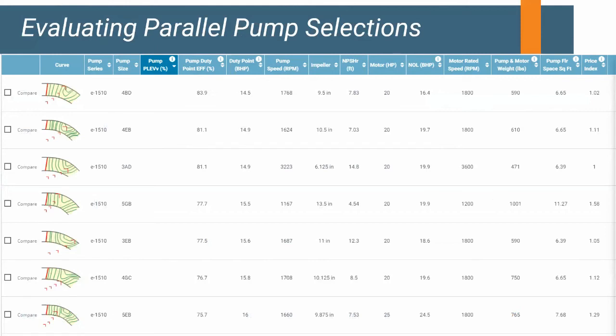Hopefully everybody's seeing that. And what I asked you on parallel pumping is, what are true statements relative to parallel pumping? Parallel pumping increases the discharge pressure. That's not necessarily true. I hate to say it. Typically when we're parallel pumping, we double the flow rate. So the discharge pressure would stay the same. Discharge pressure increases if we're running pumps in series, like we do with a multi-stage or one pump serving the next. Parallel pumping, though, we tend to double the flow rate.